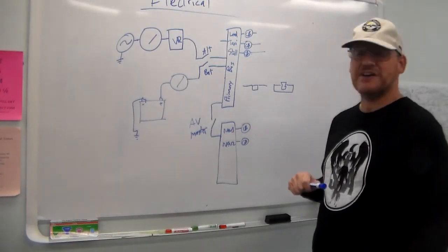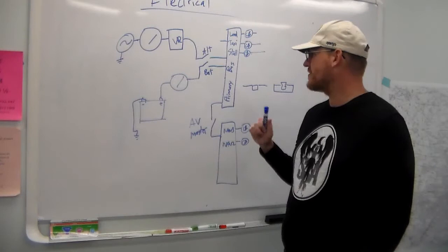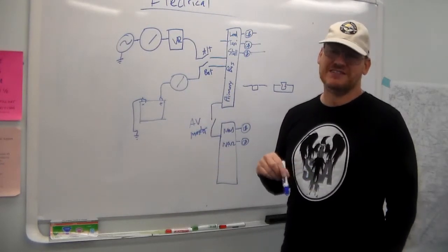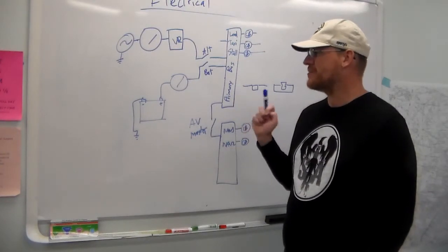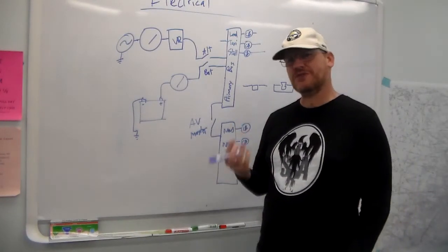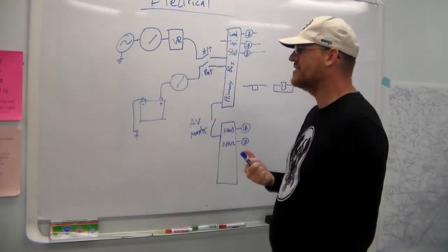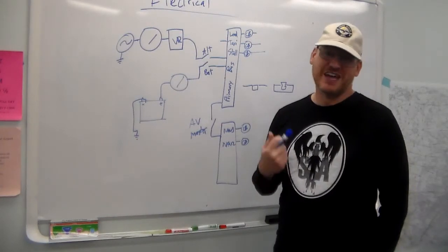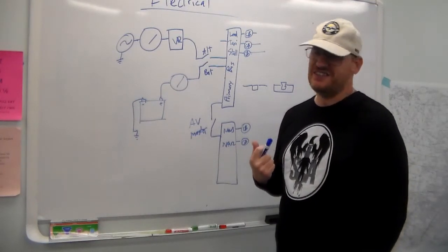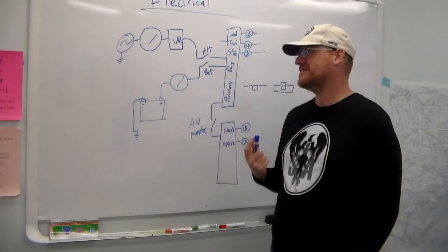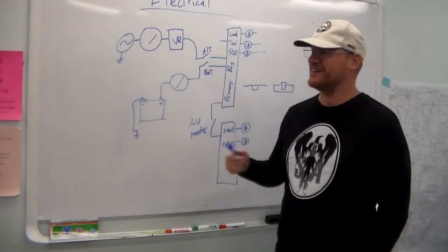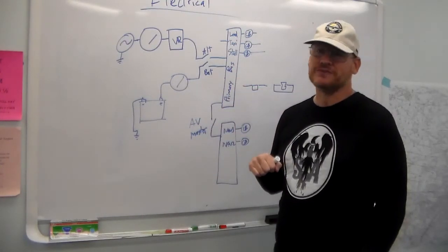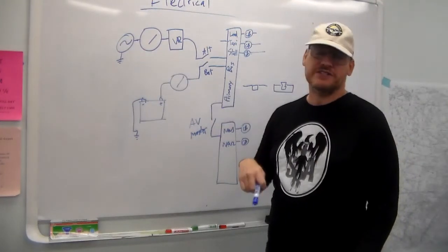Another thing that you will encounter sometimes, some aircraft will have a breaker to the alternator. You might say, why is that? Remember we said that alternators are nice, newer, lighter, etc. Normally an alternator doesn't have permanent magnets because those would be heavy and clunky. So instead of having permanent magnets, it has an electromagnet that the little loop of wire goes and spins through in order for this to produce electricity.